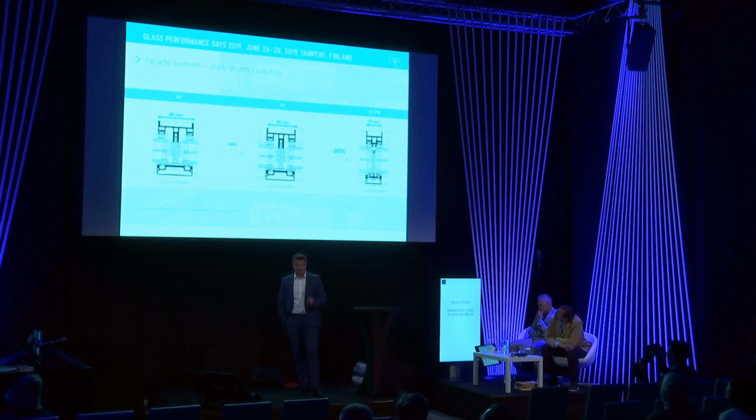Starting with a 60 millimeter, the 50 millimeter, you still can buy that. But if customers really want to follow that trend, and we see that growing absolutely, you end up at a 35 millimeter panoramic designed stick post facade. And you also can see here that with a standard screw channel, for instance, that won't work anymore. But it has not only an impact on the screws, but also on the insulating glass units that you have to bring in.